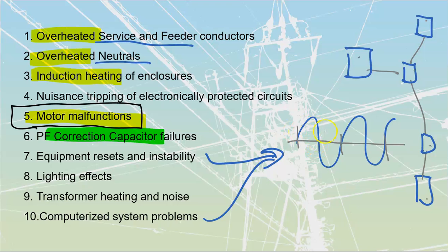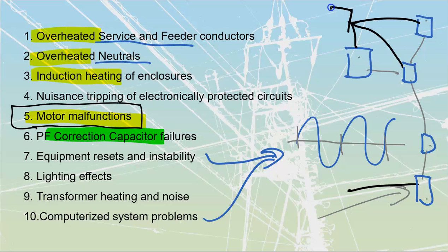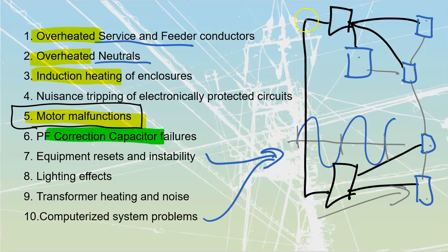The big deal is that if this frequency would change, or particularly if the frequency at just a certain section would change. These gray lines over here are my communication lines, but each of these individual components is going to have to come off of certain powers. So we've got a panel over here and a panel over here, and we could tie these two panels together off of a feeder, but if this panel has a really crappy load coming off of it, that's got crap power, it can reflect into here. It can give us harmonic frequencies, and those harmonic frequencies can trigger.